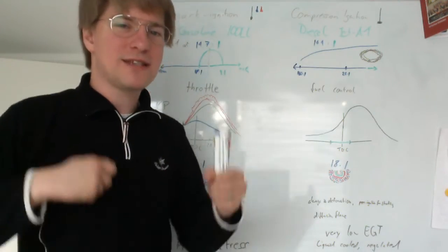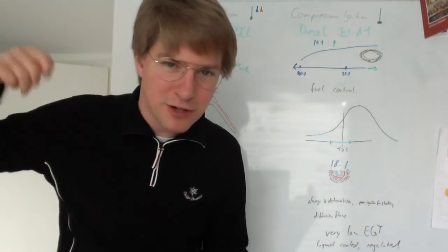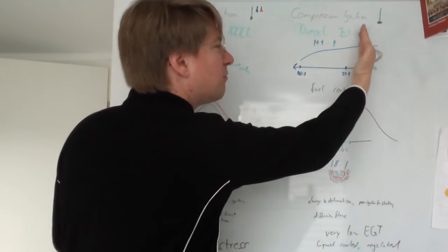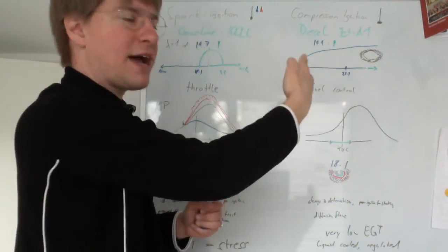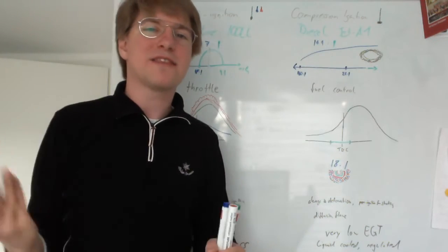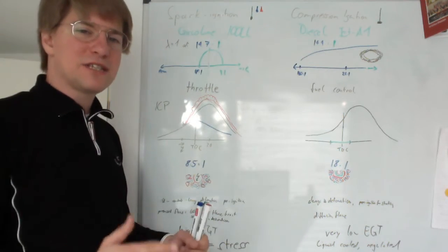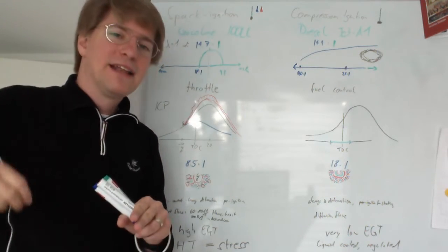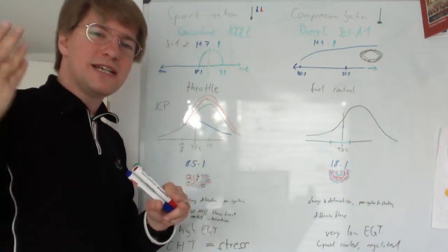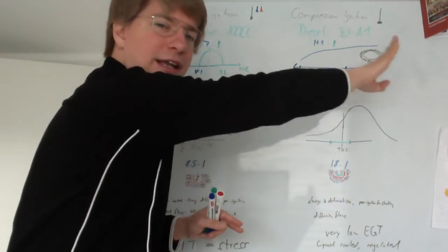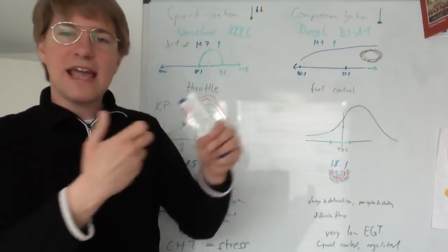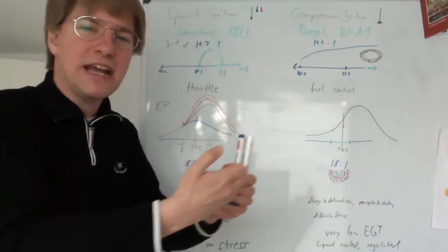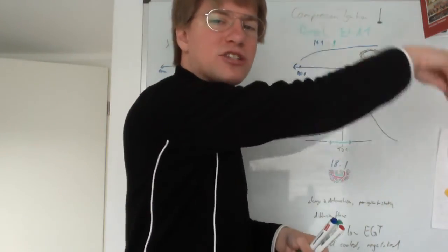Then the engine spins up, the RPM comes up. At some point, the turbocharger starts spinning and the turbocharger is injecting more air. And with the more air coming in, you're moving back out of the smoke zone, back north of 25 to 1 ratio, and the smoke stops. This is why you see when you're throttling up a diesel engine, you're not throttling it up, you're fueling it up. When you push down on the accelerator in a diesel, you get this brief moment where you're running in the smoke zone until the air intake and the turbocharger, which is influencing the air intake, have caught up with all the extra fuel you're putting in.